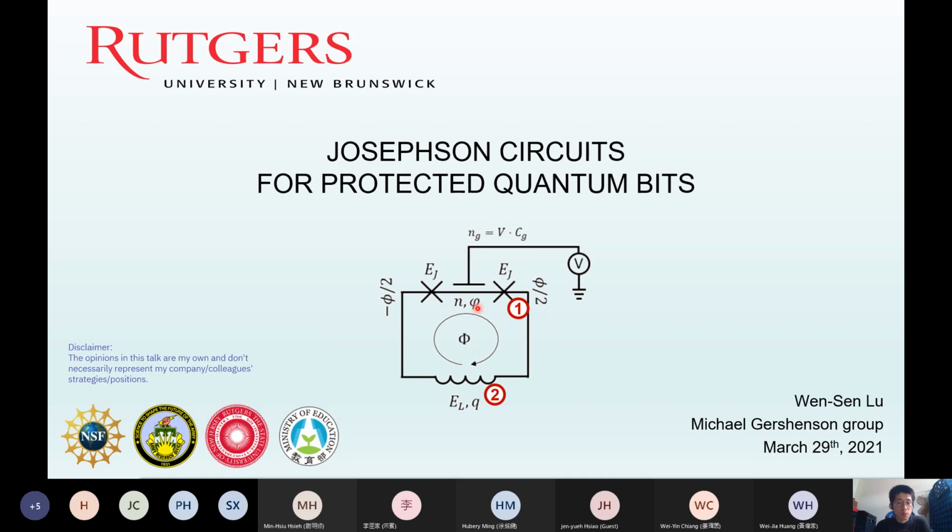So my thesis work was built around this particular superconducting circuit, the Bifluxon circuit, and in particular, I focus on two main elements to realize these circuits: the Josephson junctions with low Josephson energy EJ, and a superinductor which enables large quantum fluctuations in the phase space.